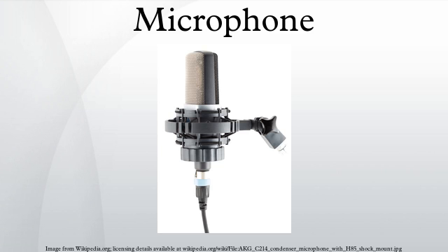A cardioid microphone is effectively a superposition of an omnidirectional and a figure-8 microphone. For sound waves coming from the back, the negative signal from the figure-8 cancels the positive signal from the omnidirectional element, whereas for sound waves coming from the front, the two add to each other. A hypercardioid microphone is similar, but with a slightly larger figure-8 contribution, leading to a tighter area of front sensitivity and a smaller lobe of rear sensitivity.